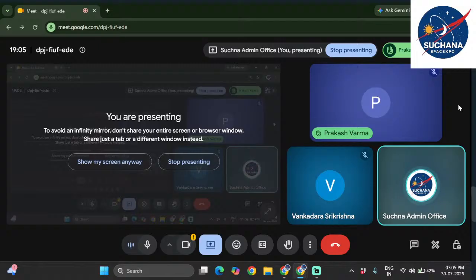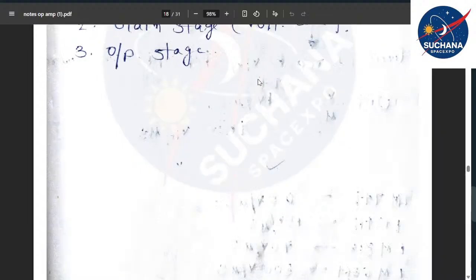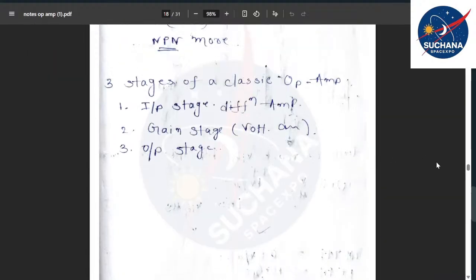The output wave is entirely dependent upon the integration of the input signal, but the final value is the inverted value because you are having a minus sign before it, right? So that means here minus 1 is the scaling factor actually. So we should not blindly say that there is no scaling factor. The scaling factor becomes equal to unity. This scaling factor can be represented with the letter A or AV. So A is equal to 1. Here it's a minus 1 because minus indicates that the signal is inverted. Okay, I hope it's clear, right? Now how an op amp can be used for the integration purpose.